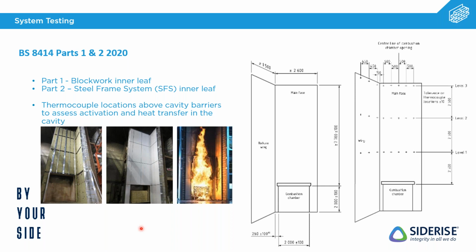So you can see there is quite a different kind of test, these system tests. You're involving all of the different components, and apologies, it's pictures there of cladding as opposed to masonry. But as I say, it's very uncommon truly to actually test to this size with masonry, as it's seen as a far more robust facade type. But you can test to them, and what you're doing is you're testing all the different components, such as any supporting structure, your thermal insulations, your cavity barriers, and then whatever that outer leaf may be.